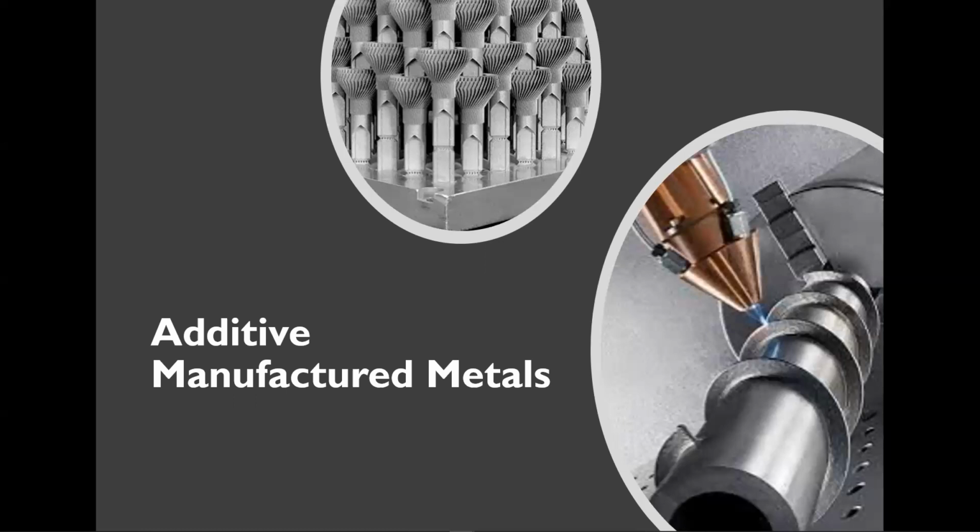And the goal for our research is coating the surface of this AM material as a post-processing effect, introducing intrinsic stress effects, either in compression or tension, whichever will be the most beneficial for the post-process, to increase the fatigue life and not decrease the yield strength in these AM materials, to better resemble the as-built similar compositions.